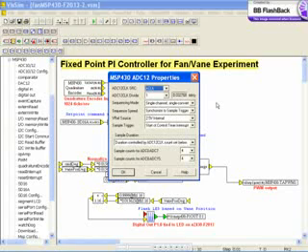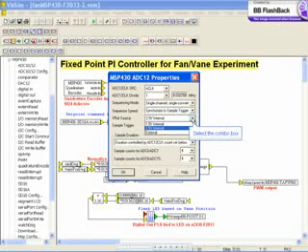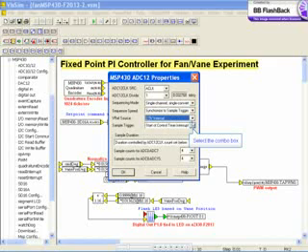Depending on the CPU subtype you select, you will either see an ADC10 or ADC12 configuration. Selecting your source and divider determines the rate for the ADC clock. You can select your sequencing mode, sequence speed, your voltage reference, internal or external, and your sample trigger.